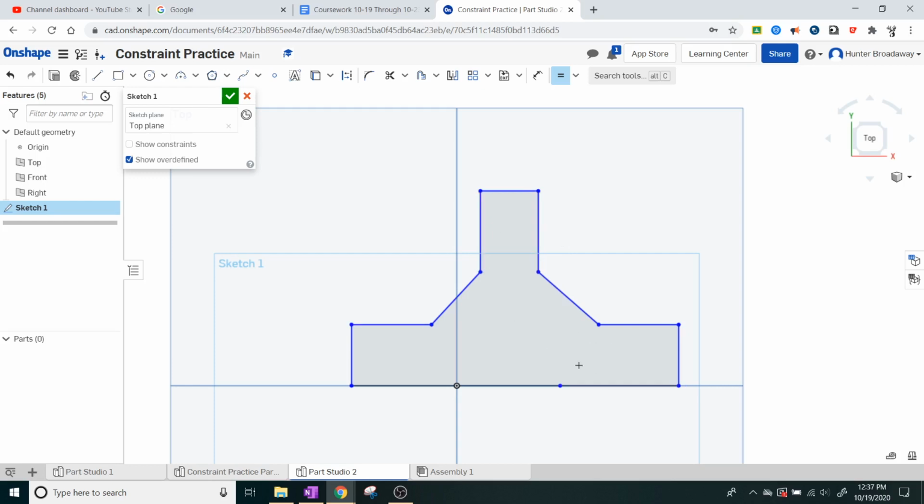Okay, and then from there, if I move these around, those lengths will automatically be equal to each other, which is nice. So I can move this up. I can move this down. And I can also use the equal constraint with these as well, because it doesn't look like those two lines are exactly in the middle with each other. So I'm going to hit equal, and those two lengths should kind of match up. Now this looks like a very nice symmetric object. Now I'm ready for number 23.